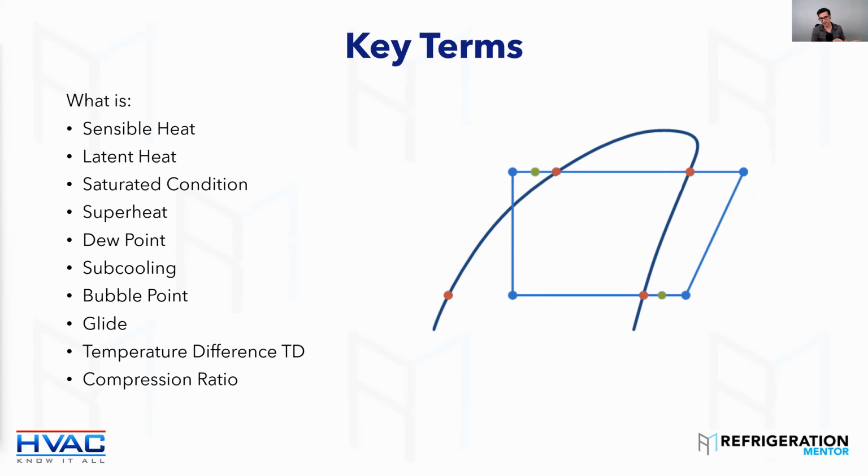On air conditioning scrolls, it's 11:1. If you work on 410, like Gary just said, it's like 3:1, 4:1 all the time. But when you get up to 11:1, that's when it's going to unbalance that floating seal. So when you're on your AC unit, you're trying to pump it down, and all of a sudden you get down to 25 psi and it goes to equal. That's what's happening. There's nothing wrong with the compressor. You're putting it outside its operating envelope.